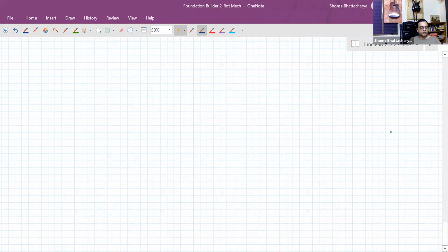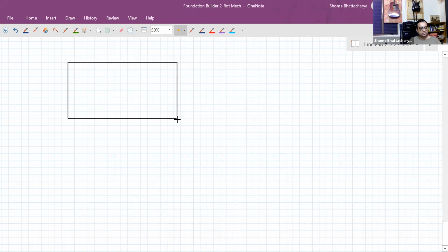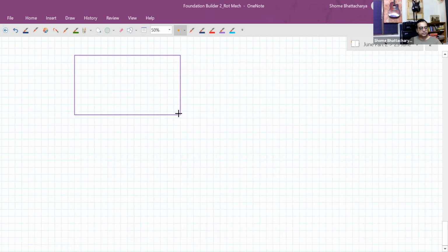Now we can also use these results for some more examples of applications. So for that same rectangular plate, for example, we want to find the moment of inertia about either of the edges, then we can do this. We can use parallel axis theorem. So for example, now if we take this as our axis, then we can compare this with the parallel axis passing through the center.